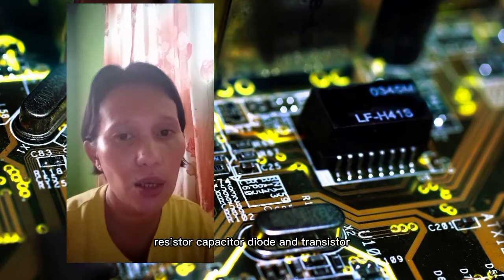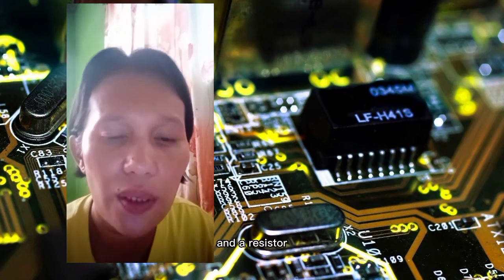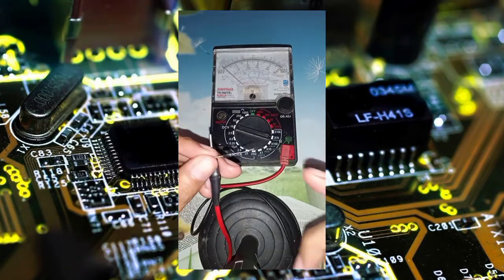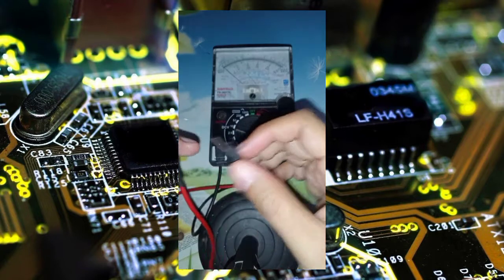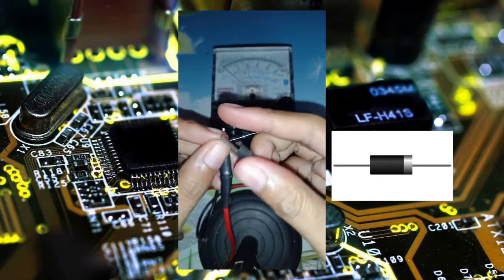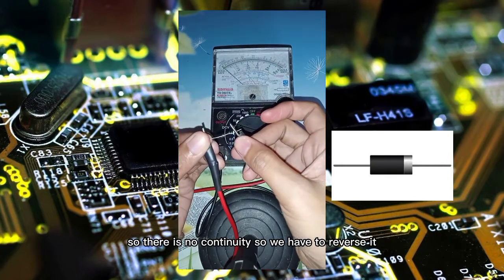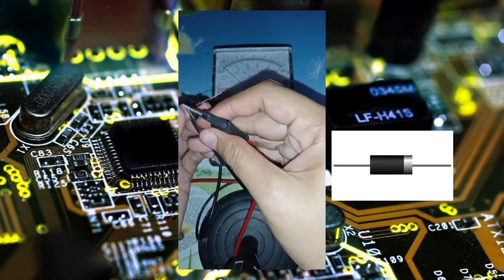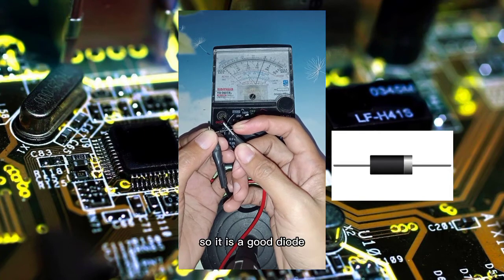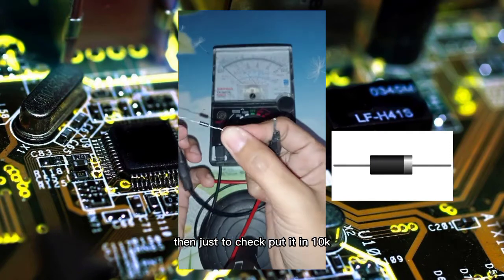There are just 4 basic components in electronics: resistor, capacitor, diode, and transistor. I am only showing you on how to test a good diode and a resistor. So now I will be showing you on how to test a good diode. First, you have to set it in 1K. Then test it. So there is no continuity, so we have to reverse it. So this diode has 5 ohms, so it is a good diode.